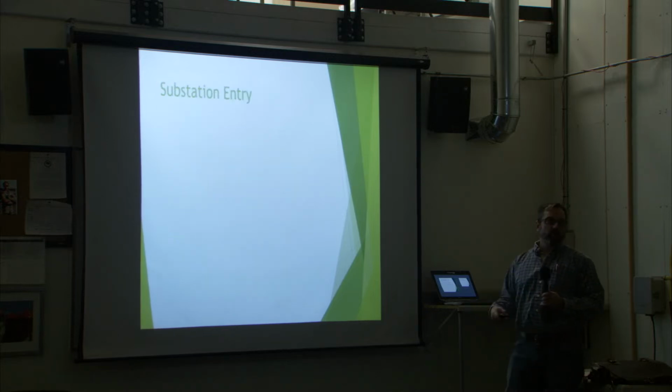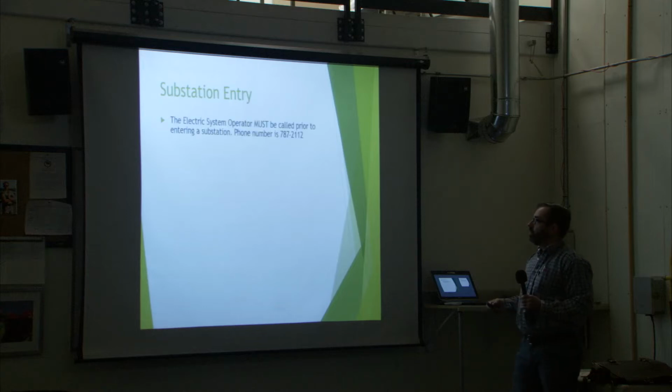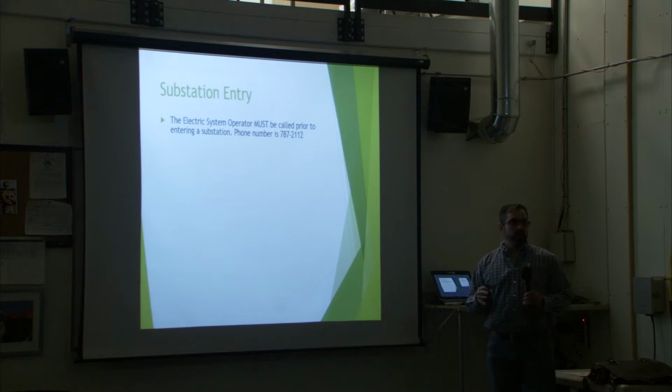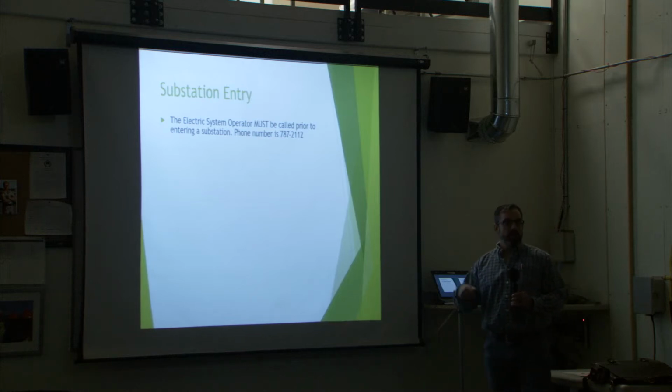Okay, so we've kind of gone over some of the components of a substation and a few of the hazards associated with it. So let's talk about substation entry. Remember, not just with substation work, but with all utility work, communication is the biggest safety factor for us. So before you enter a substation, make sure you call the system operator. The operator is the only person between you and the system who knows that you're going to be in the sub. If everybody doesn't have the number in their phone, they should have this programmed.